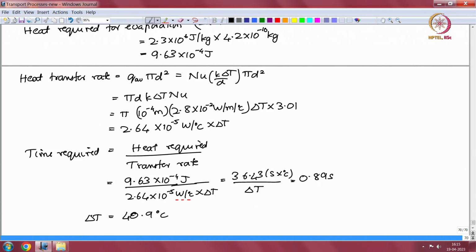Okay. So, this is an example of how you design a combined heat and mass transfer process, so that the entire heat transfer gets completed. The temperature difference is sufficiently large that there is heat transfer from the gas to the droplet within the time that it takes for the mass transfer to take place due to diffusion.